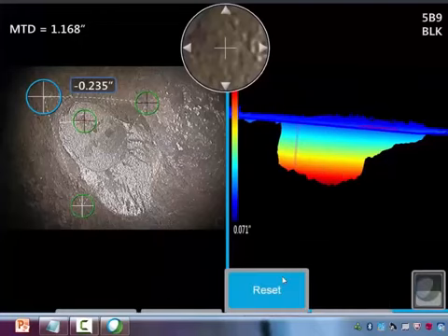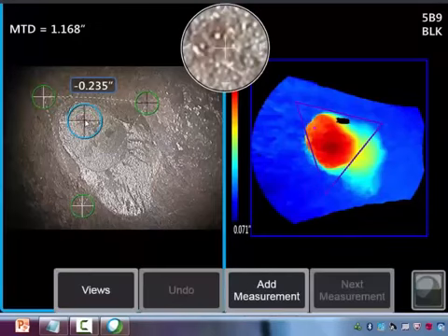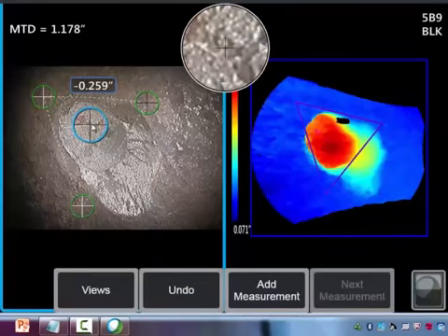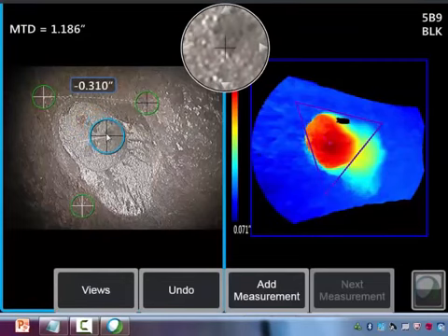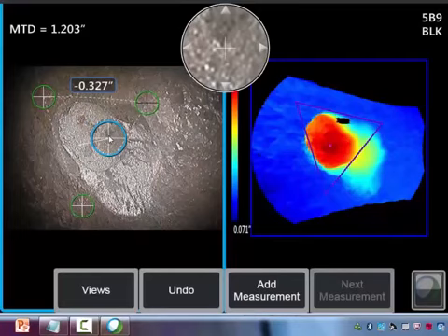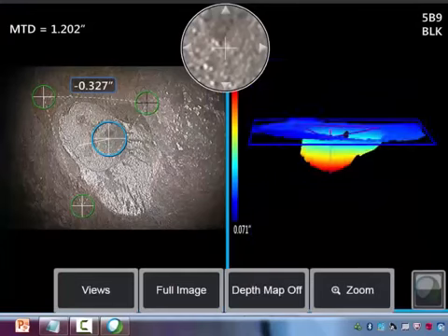So, seeing that, we can come back over to the left side and reposition this fourth cursor, using the point cloud as our guide, to get that measurement over to that deepest location. While we can get there that way, that is kind of a tedious operation.